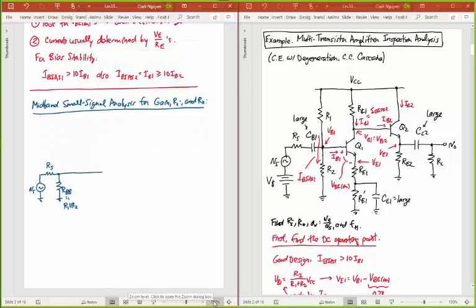Okay, then I have my transistor Q1. You can see that this capacitor CE1 shorts out, so I get rid of this RE1 prime, but I'm left with RE1. So I still have RE1 there, and then I've also, with this transistor, have a collector resistor, RC1, that's going to ground there. And beyond this, I then can come out to my,